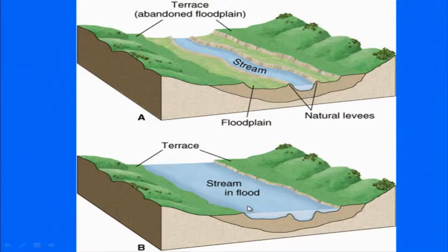But one thing which you can remember, that usually the older terraces are the safe areas where the flooding will not usually affect, but the low lying terraces close to the stream can be inundated by the flooding events. So this areas close to the river, even though they are terraces sitting at the higher elevation, should be avoided, but these are much higher, which are the older abandoned floodplains. So, such areas are good for habitation.